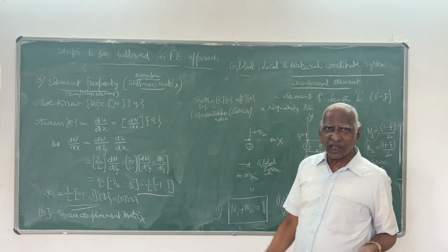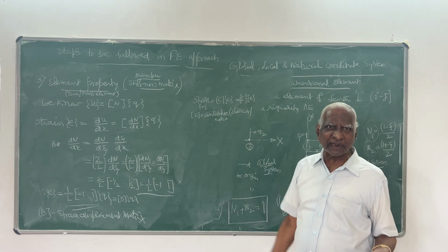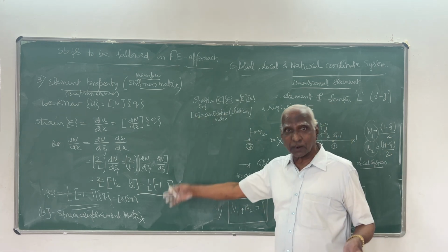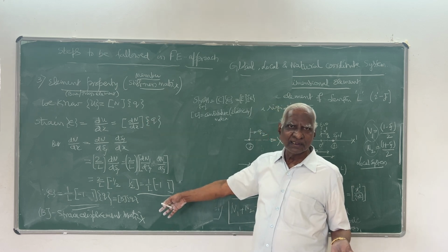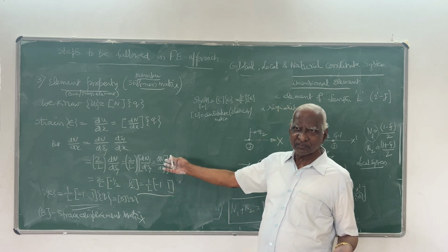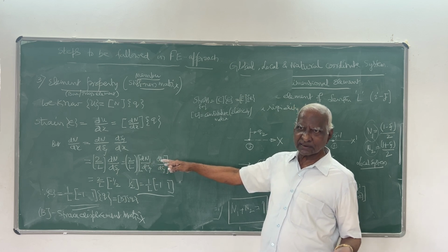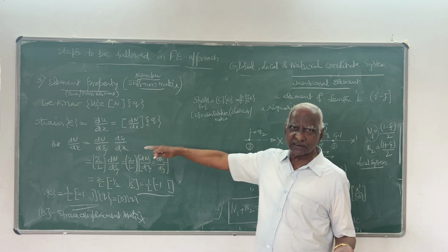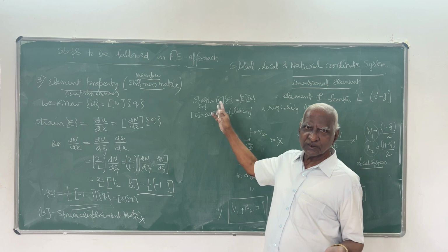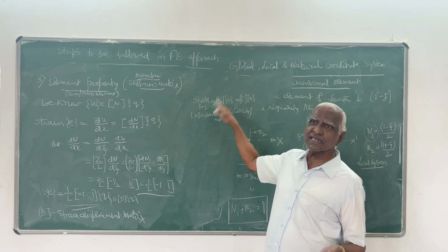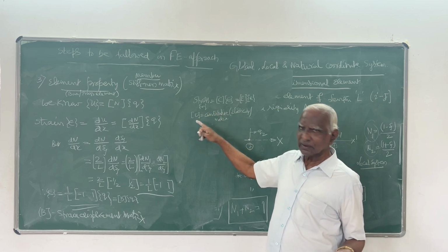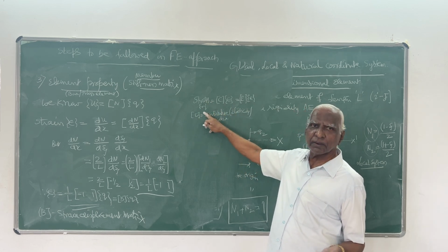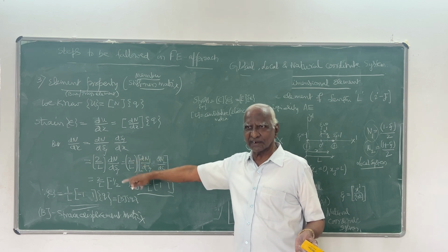Or in general, the constitutive matrix you have to take. I am writing the general procedure: displacement model, from that strain using the strain displacement relationship, then stress using the stress strain relationship.